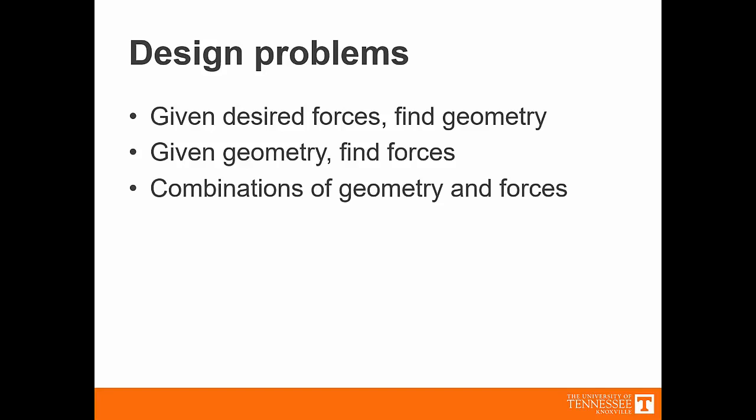So very often you're told we need to have something that responds with 10 pounds of force, and you can define the spring and how much compression it can have. Or maybe you're told the spring is going to compress 4 inches and you need to know how many pounds it's going to push, or something. More often than not, it's a combination of the two. So we've got room to put a 4-inch by 2-inch spring in here, and it needs to resist 10 pounds, something like that.